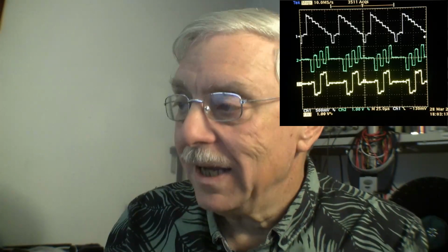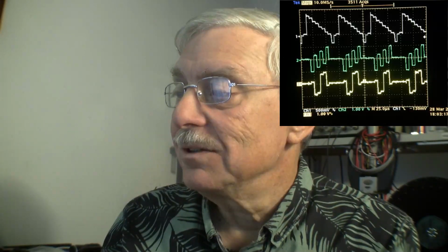Now, using color bars and an oscilloscope, you look at the waveforms that I've drawn out here, and you can see them on the oscilloscope, and that's what we're looking at now. We're looking at the Y, R minus Y, and B minus Y signals, or actually the B minus Y and R minus Y. I've got my scope probes backwards.